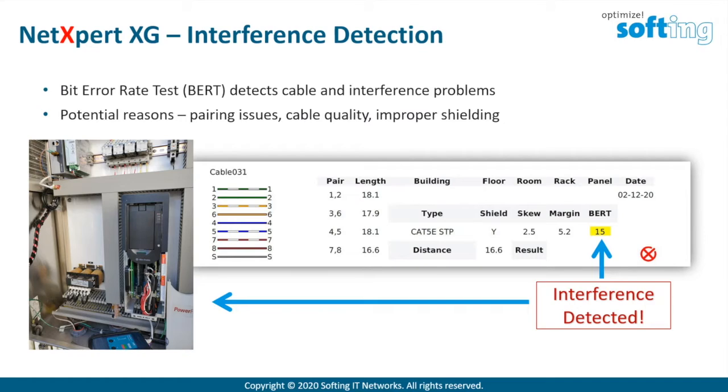So I point this out because all their other test gear and the folks that tested that cable, everyone confirmed that it's not the cable. We ruled it out. It must be something else. Well, what could it be? Well, 1,000 different things. No, it was the cable. They just didn't apply the right test to it, which is the bit error rate test. I like to emphasize that because that happens more often than not in the industrial environment, especially in industries where there's a lot of noise, like drives picking up harmonics.